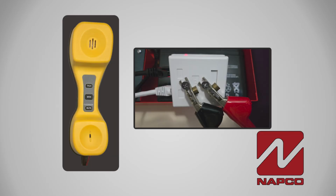After you tap the line, you will put your butt set on talk and listen to verify there is a dial tone. The dial tone will go out and then come back on.